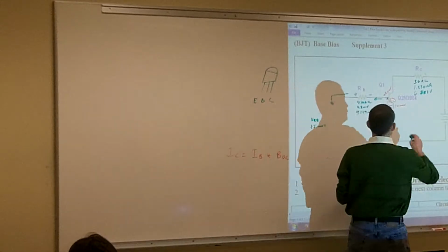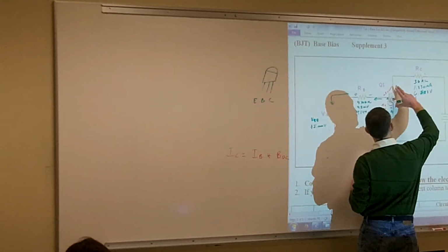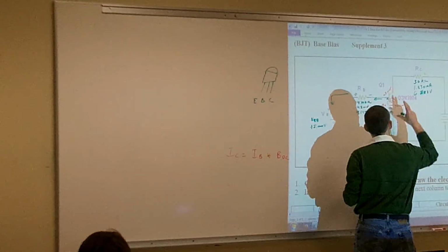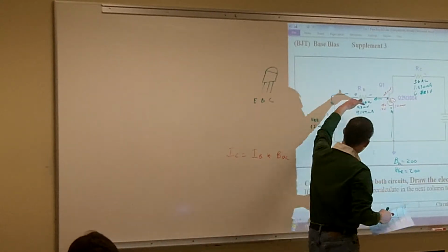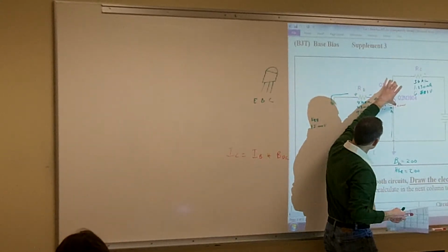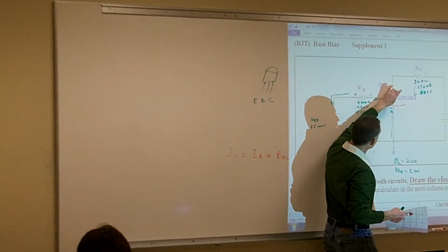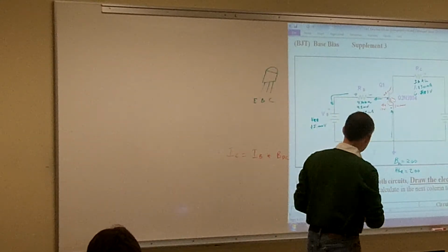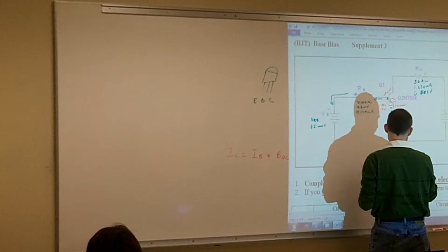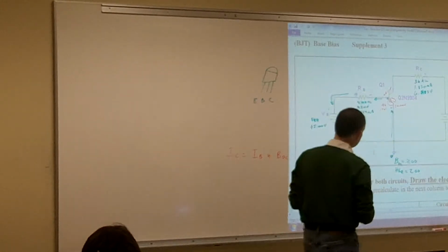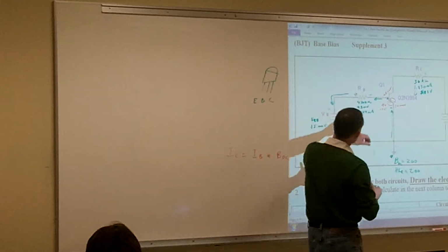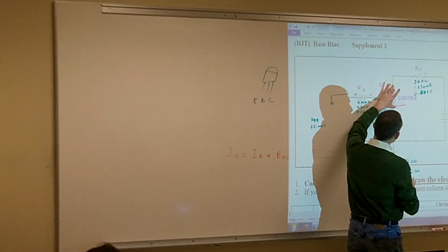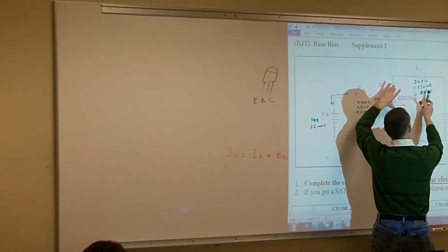Now what we have is this junction here. This is our collector to emitter junction. Our voltage across our CE. As I start driving that harder, that resistance across this collector to emitter is going to automatically vary. For approximations, it's going to try maintaining this beta DC of 200. That's the built-in gain of that transistor. So this transistor is automatically going to change in resistance so that we get 200 times more current on our collector.